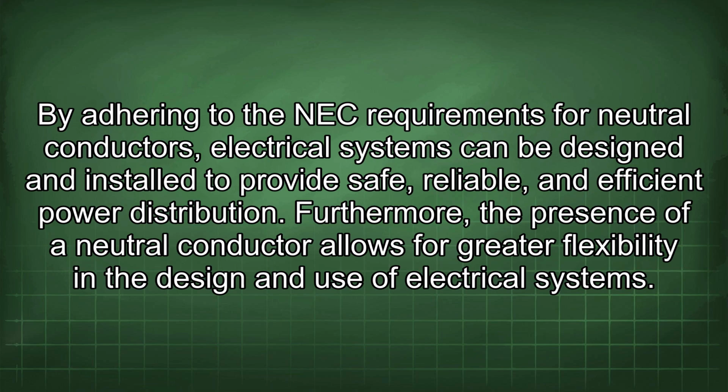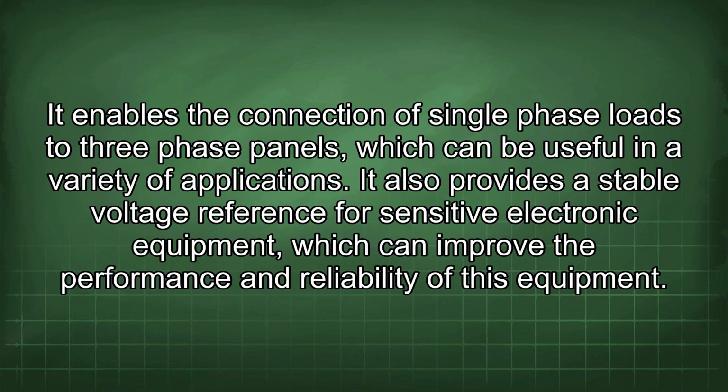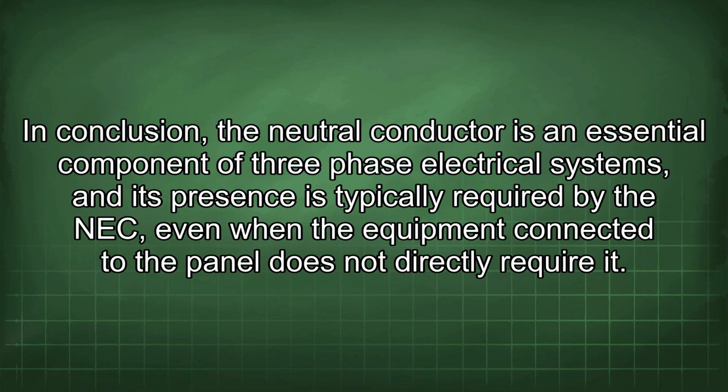and efficient power distribution. Furthermore, the presence of a neutral conductor allows for greater flexibility in the design and use of electrical systems. It enables the connection of single-phase loads to three-phase panels, which can be useful in a variety of applications. It also provides a stable voltage reference for sensitive electronic equipment, which can improve the performance and reliability of this equipment. In conclusion, the neutral conductor is an essential component of three-phase electrical systems, and its presence is typically required by the NEC even when the equipment connected to the panel does not directly require it.